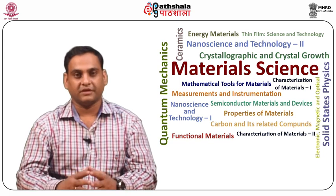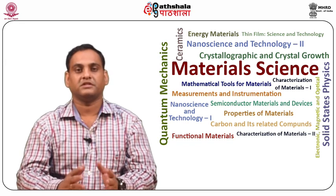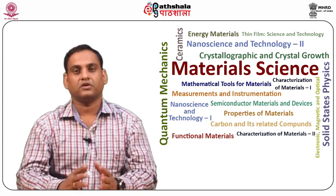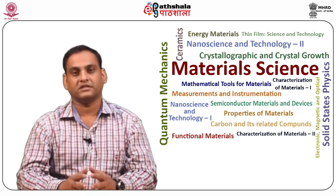Apart from the soft magnetic applications, these materials are used as magnetic refrigerants based on the principle of magnetocaloric effect and are also used in magnetic impedance purposes. Conventional methods of improving the intrinsic and extrinsic soft magnetic properties have been focused on tailoring composition, control of microstructure with heat treatment under different environments, reduction of Hc, that is coercivity, increase of saturation magnetization Ms, and control of intergranular exchange coupling in the amorphous and nanocrystalline materials.